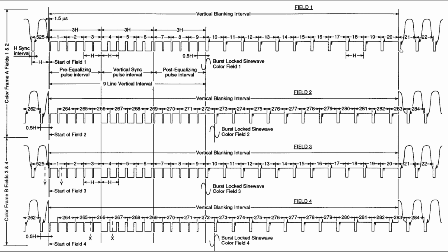These are the sync pulses. And your video information is these humps right here. So the higher this, the brighter the screen, this line. In this example, this line would be fairly bright all the way across. All right. So that's pretty much what we have to generate.